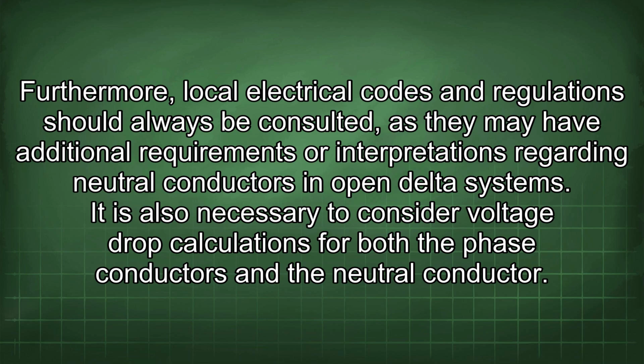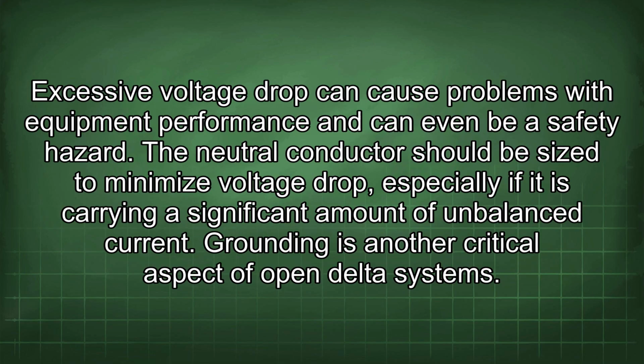It is also necessary to consider voltage drop calculations for both the phase conductors and the neutral conductor. Excessive voltage drop can cause problems with equipment performance and can even be a safety hazard. The neutral conductor should be sized to minimize voltage drop, especially if it is carrying a significant amount of unbalanced current.